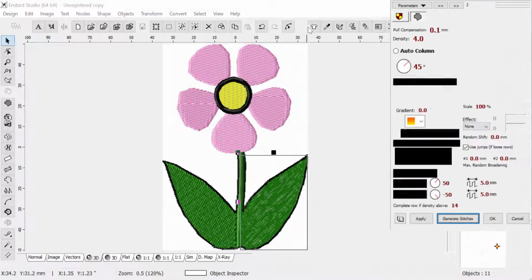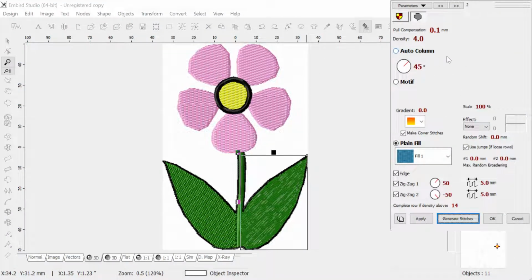The other parameters there, you usually don't need to change them, but I'll just note the density basically tells you how many stitches you have. Usually 4 is the standard, so you don't see anything beneath that. It's not too dense, not showing anything beneath that. If you want whatever is beneath that to be shown, or the fabric being shown through the stitch, you're going to increase this density